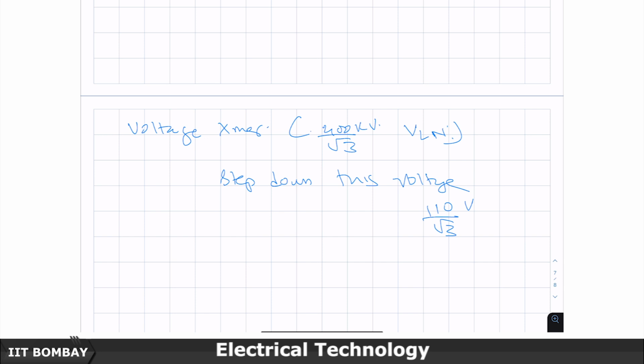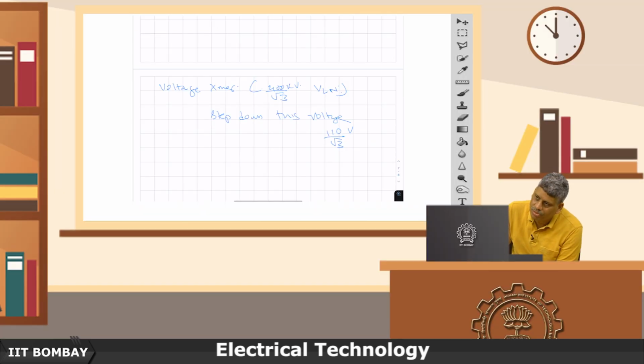These numbers have been standardized from past times when you used to have relays which were driven by these instrumentation transformers. If you today look at the electronic instrumentation that we have, these numbers could be much lower. There is no harm in having these numbers at a much lower value, but since this has become a standard, this is the way it is kept.